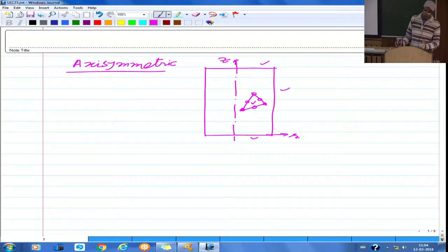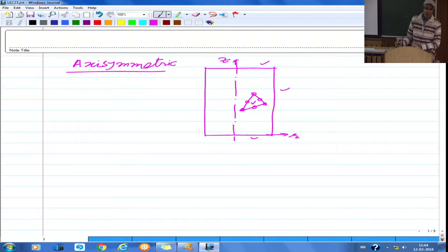As long as you use a sufficient number of elements, all elements will give you the accurate solution. The only thing is computational cost would be more in one case and less in the other, because the number of elements and overall degrees of freedom would be less if the element is based on higher degree interpolation.